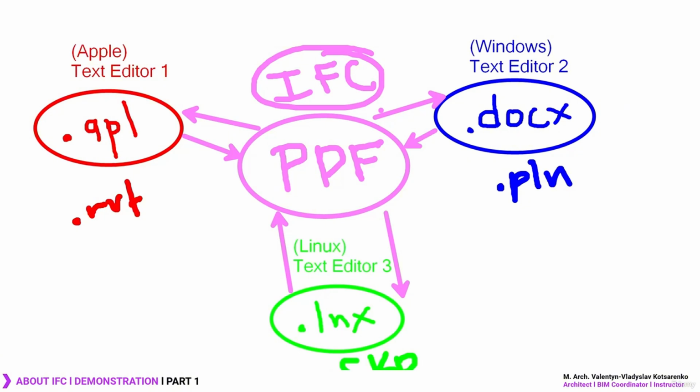Now, of course, when you export into IFC, it's possible that some data loss will happen. So that's a thing to keep in mind. Data loss will always be present. This depends also on the importer and the exporter for each software. So some percentage of data loss will be present unless you configure this as best as possible. But the most important thing here is that now everybody is happy because everybody can share different types of BIM models and information across multiple types of platforms.